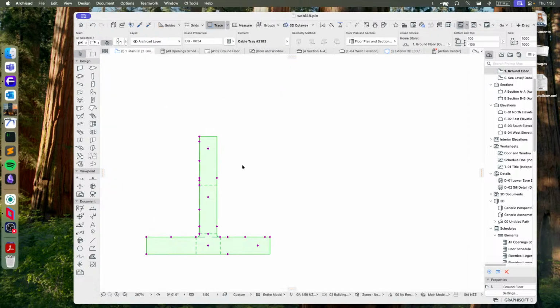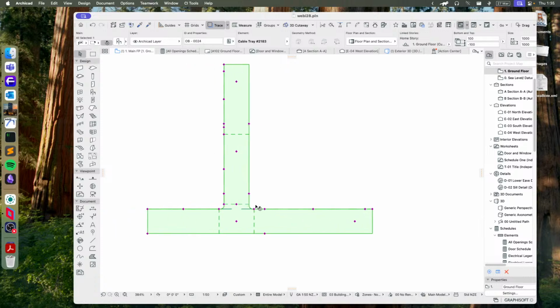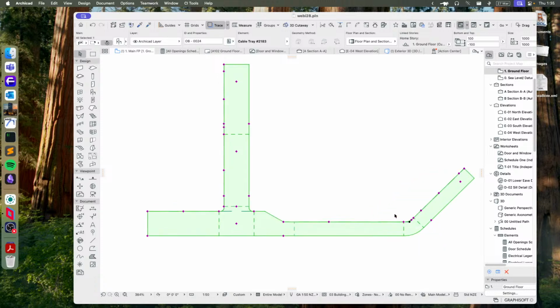So it will by default show this T shape. We get plenty of options about how it works, and we have hotspots for the nodes, so we can adjust the length of pieces. We can add in reducers by moving this hotspot here. We can split edges by moving this hotspot here. We can add additional edges, turning around corners and things using this one. Everything is locked to 15-degree increments, and we can use the last hotspot to adjust the other edge's length.